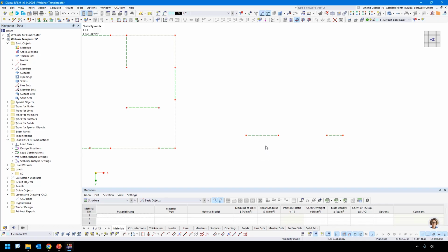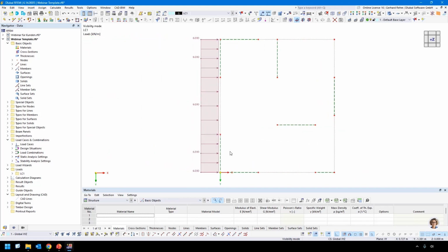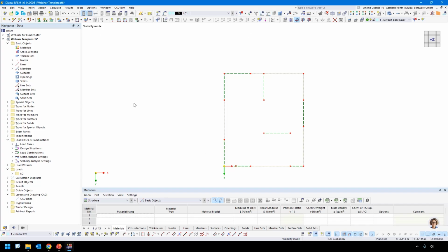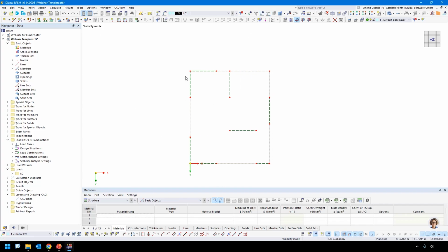Yeah, but because of all these components which I showed in the first webinar, we assume that the stiffness of a timber frame wall is proportional to its wall length. And this helps us in a simple way that we simply can define some supports, nodal supports here at these wall locations. So I have defined it already.